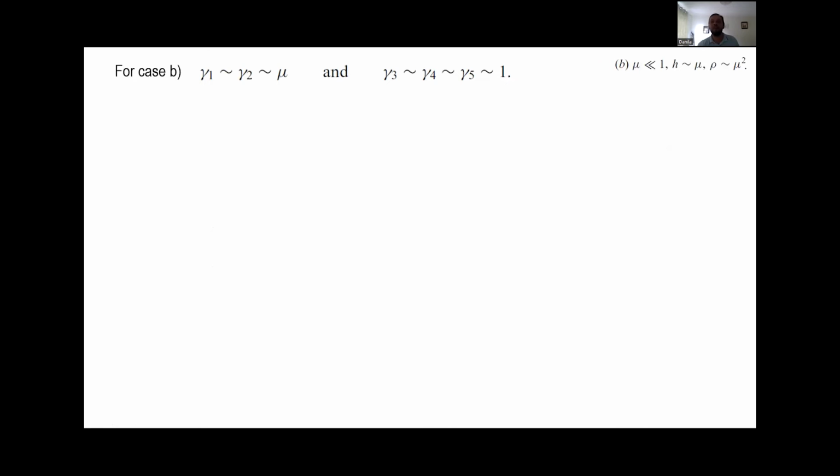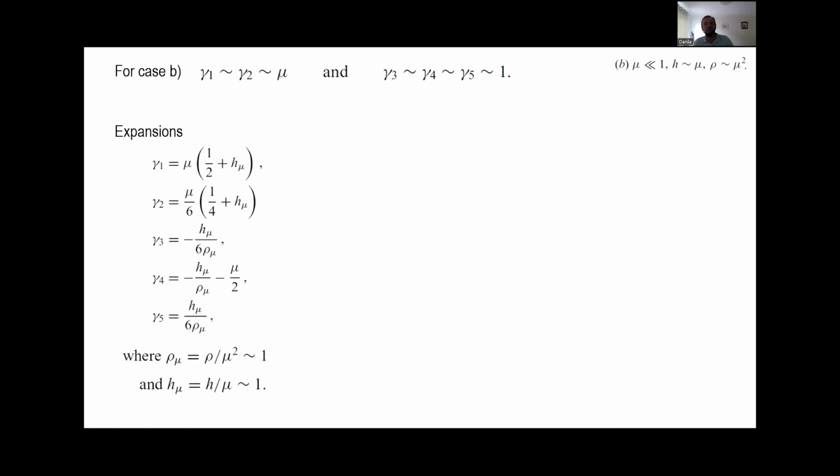Okay, so now the second scenario for the sandwich type structure is quite different. And as we can see here, first of all, these coefficients here, gammas, not all of them are order 1. Second thing, when we start and derive approximations, there are some internal cancellations. So as a result of that, we really need to keep the second term here for gamma 4. And also, we have some more of these dimensional, order 1 quantities here.